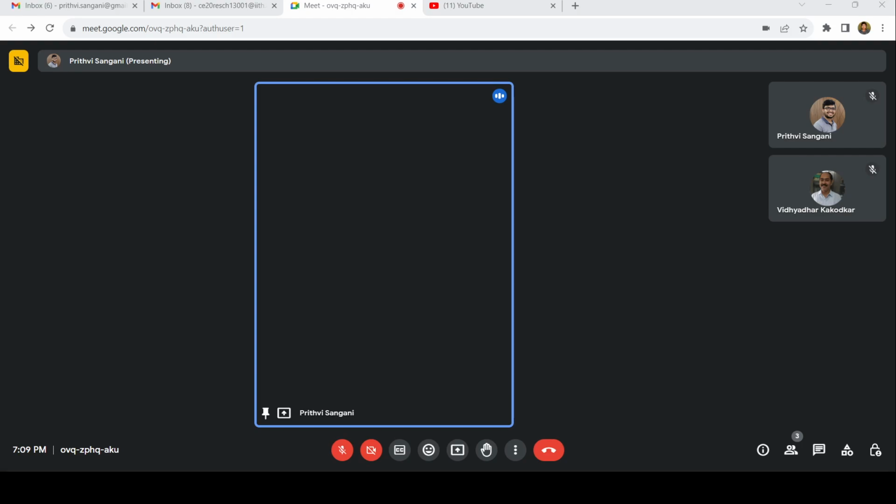So you should not have any relative displacement inside, right? There can be shortening, or maybe the member can stretch by itself due to internal forces, but there should not be any relative displacement between the initial delta 1 and delta 2. So delta 1 plus delta 2 should be 0, and by using that equation, you can find FBD, which is the redundant force. So I'll call this 1, and this is 2.